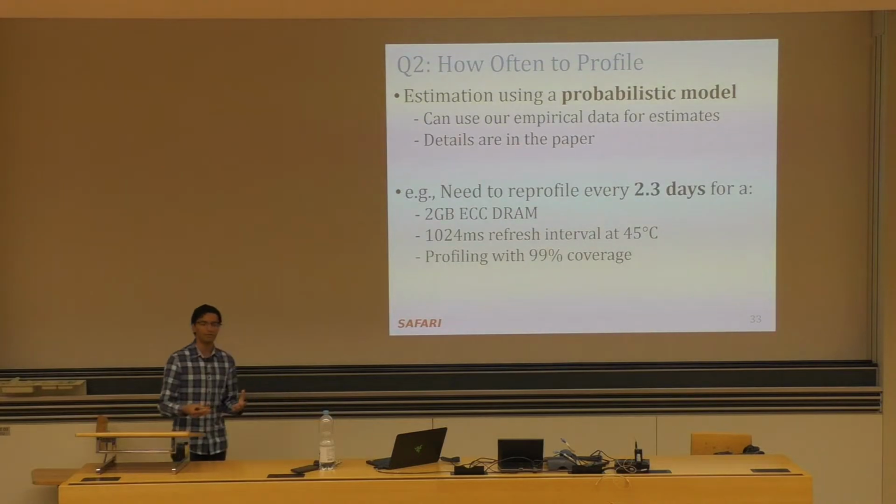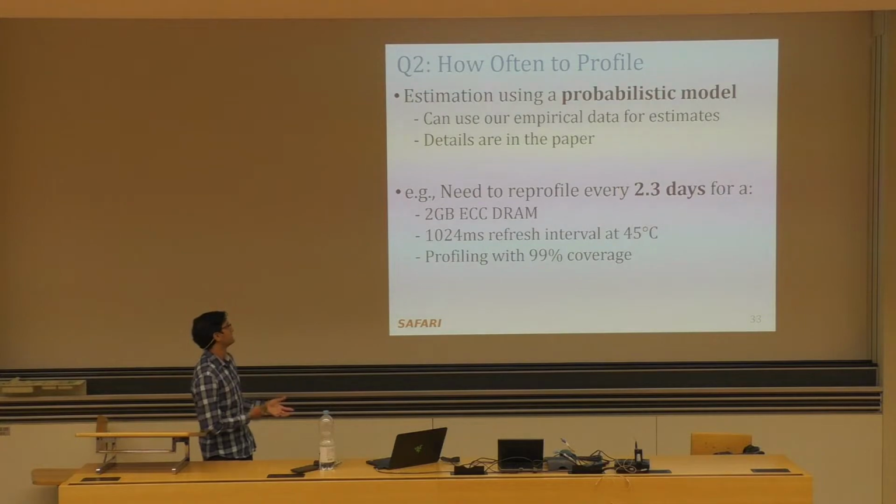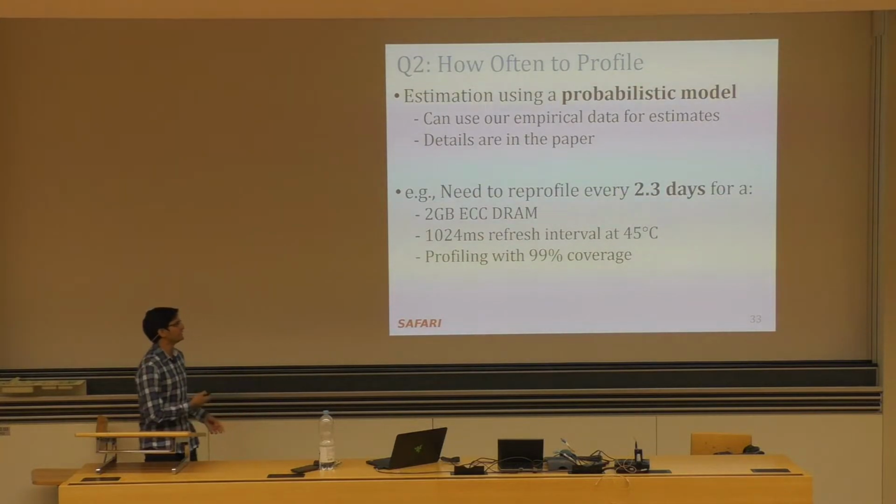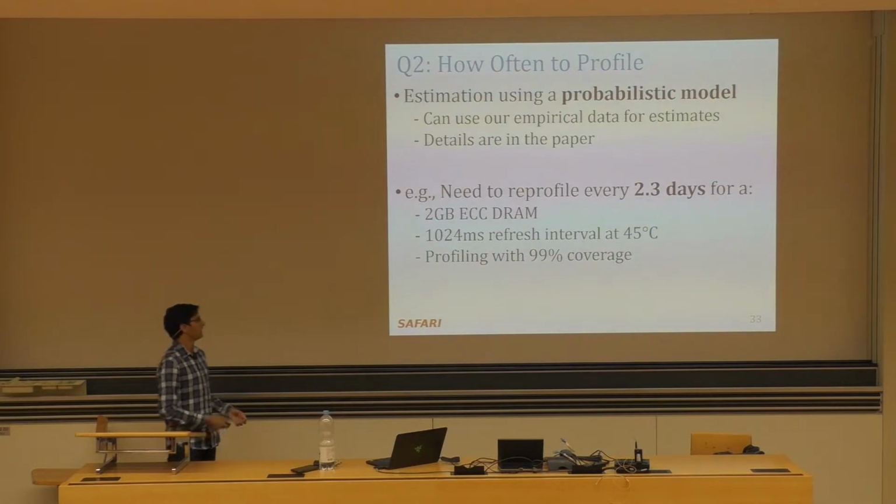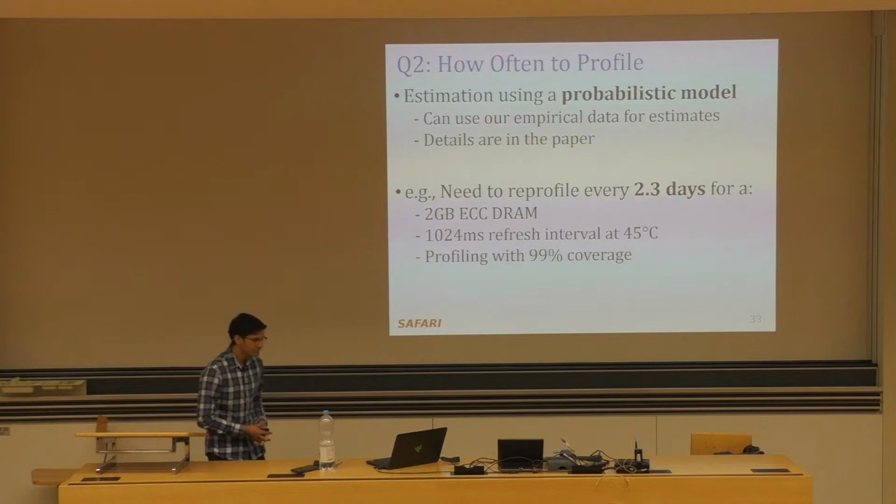And as a specific example, just for your point of view, we need to reprofile every 2.3 days for the configuration shown here, right? And this is a pretty aggressive increase in the refresh interval from 64 to 1024 milliseconds, right? And maintaining 99% coverage of errors.